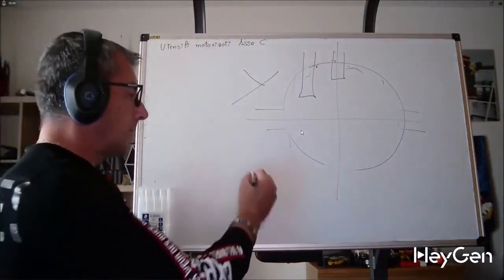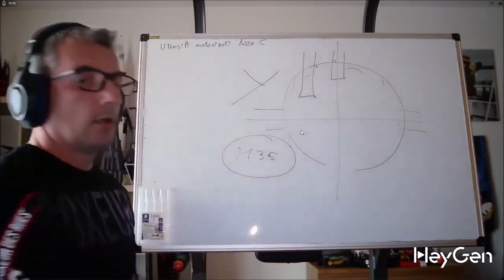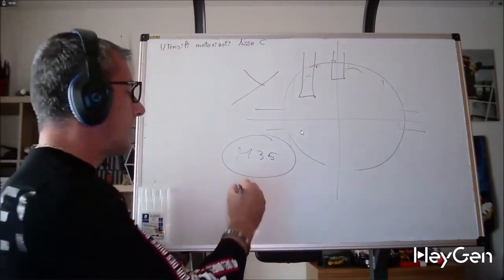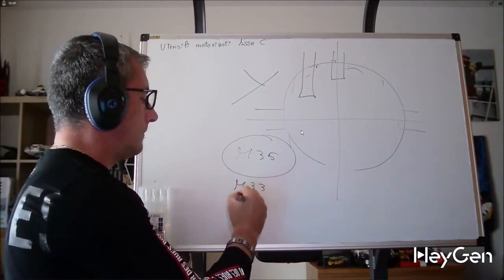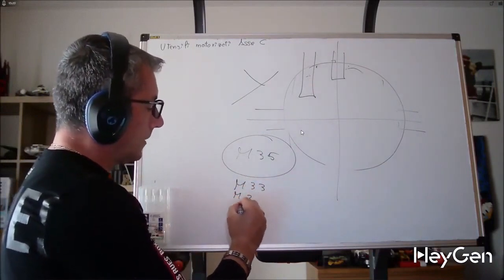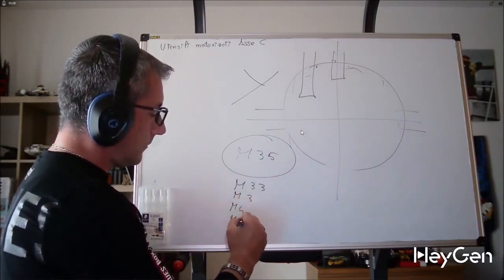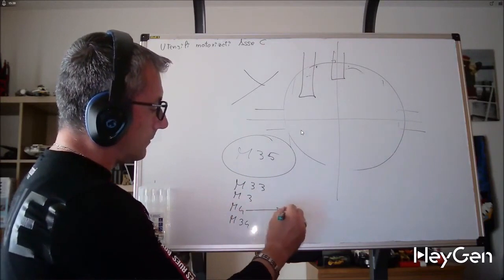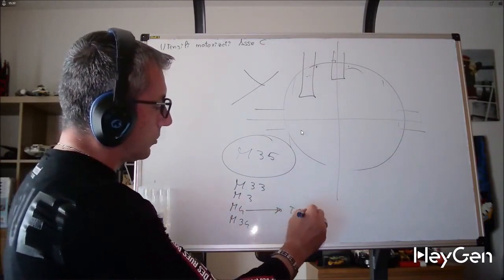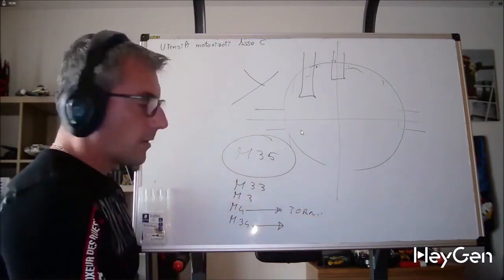We need to use M35 to activate powered tools, and on some machines, M33 instead of M3 for the spindle, or M4. M4 activates the lathe spindle, and M34 rotates powered tools. On modern FANUC machines, M4P11 activates the spindle, and M4P12 activates powered tools. The main difference is using G112-113 commands for Cartesian axis. Viewing from the front, but this is not a problem.